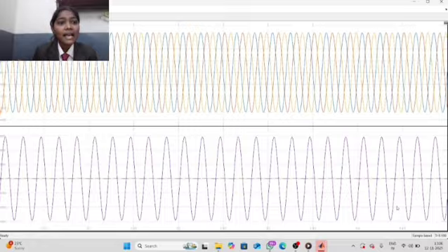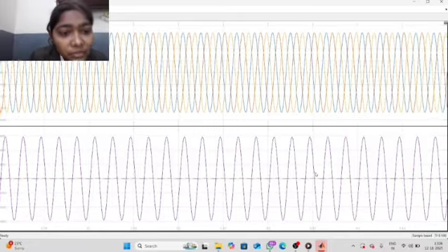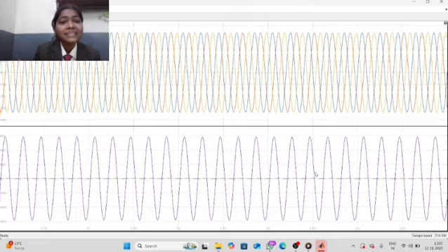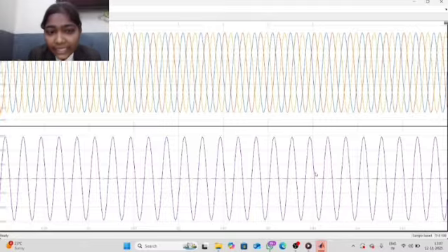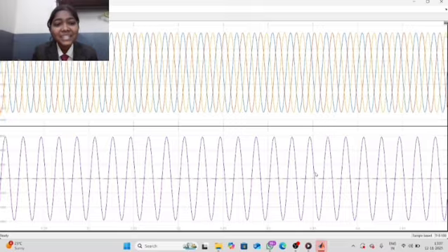I am Gaikwad Sejal. I am explaining the output waveform. The first one is the three phase waveform, and the second one is the single phase waveform. The output waveform looks like a sequence of chopped sinusoidal segments. From this waveform, if the input is 50 Hz, then T equals 20 ms. For the output waveform, for example 25 Hz, T equals 40 ms. Hence, the output waveform has half the frequency and controlled amplitude.